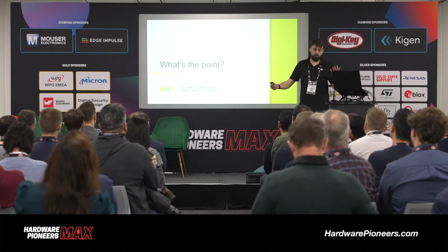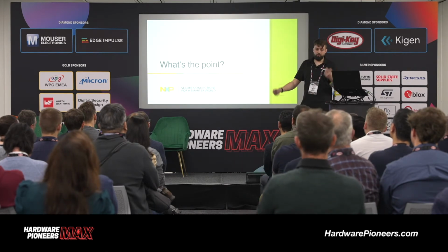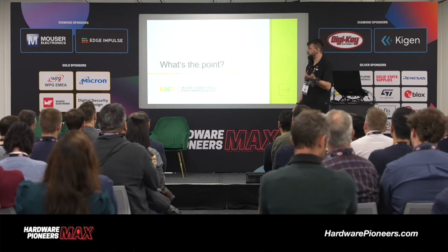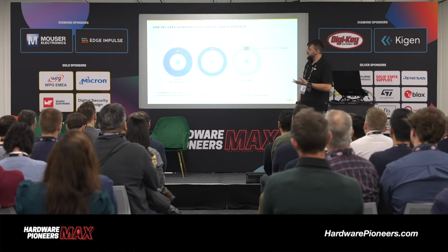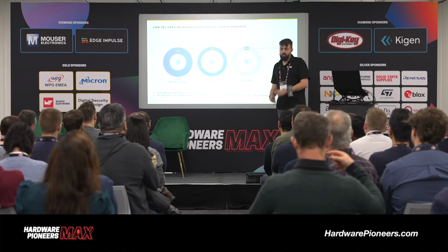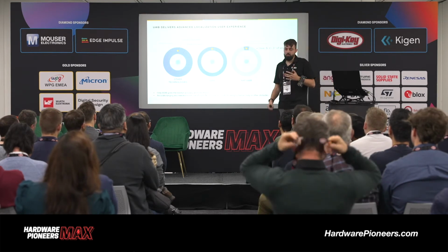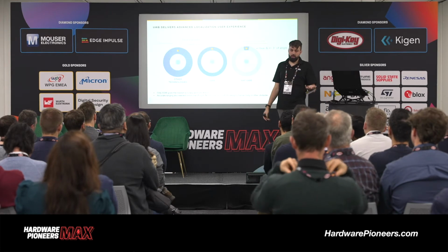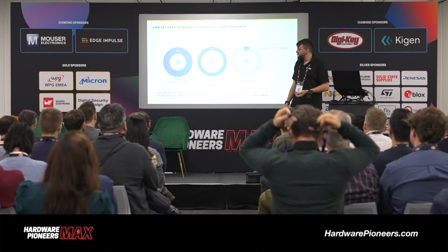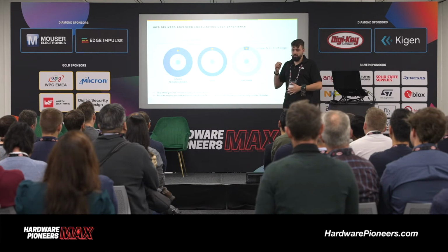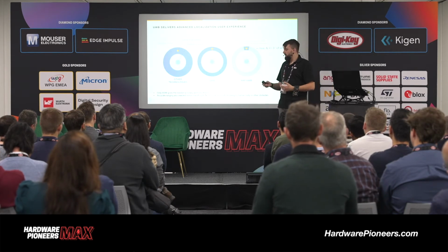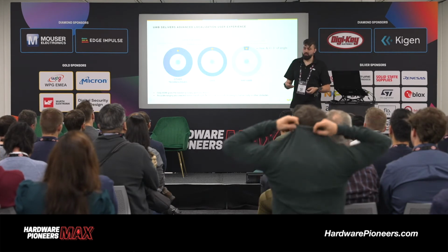So what's the point? You can do multiple measurements. What can we use that for? In the end, it's about a finer location. Other devices, Bluetooth and Wi-Fi, can mostly do accuracies of up to plus minus 50 centimeters. With only ultra-wideband, with only distance measurements, we can do accuracies of plus minus 10 centimeters.